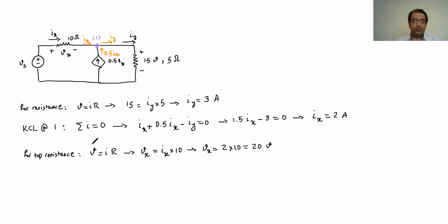So if I want to use that to find the voltage here, what the Kirchhoff voltage law says is that if I choose a loop and go through that loop, and add all the voltages together, it's going to come out to 0. So if I add all the voltages, then it should be 0.